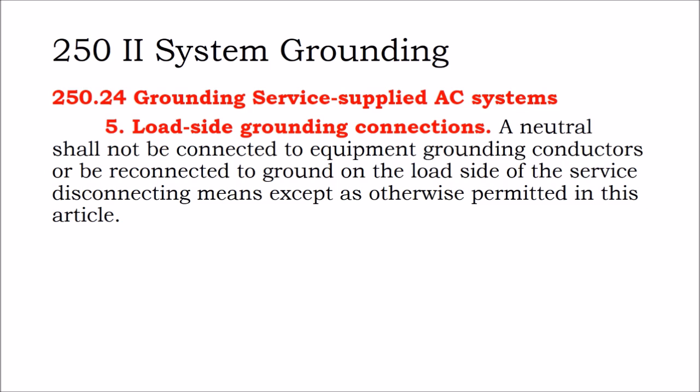What that means is if you have a lot of experience in the utility sector, you may be hanging your own transformers and then establishing a connection to ground on your new electric service. Then you get out to an existing electric service and you will not be providing that neutral bond to ground because it's already made if you're coming into an existing neutral service. So you just have to be on the lookout for that.